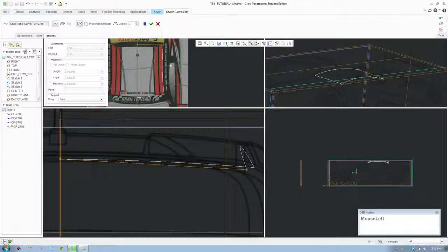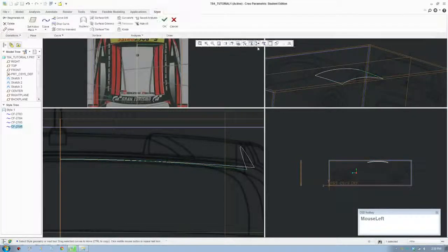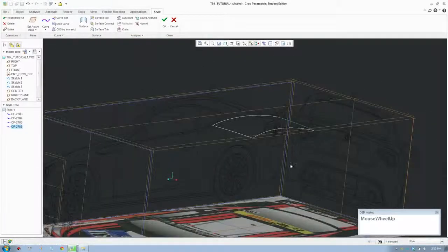We'll do the same for the other line. Click the other line to edit that line, turn on the control points, put this onto horizontal, and make the points evenly distributed. Make sure your points are evenly distributed, and don't put too much extreme curvature on it. It won't look well.